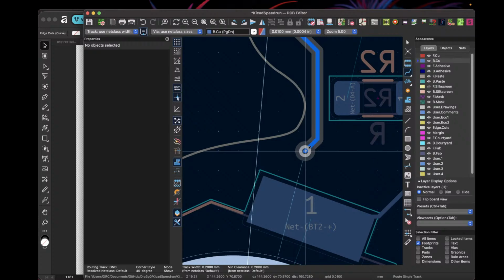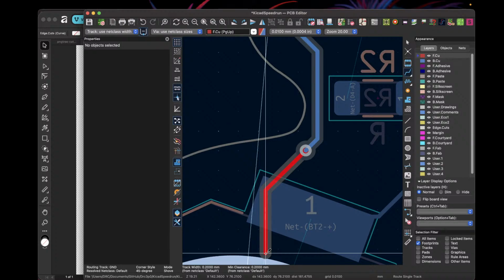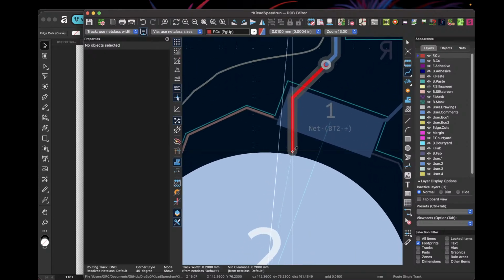Is there a downside to vias? Like, can I just easily jump over any other wires? They're usually okay. It's just, again, if you're dealing with something where maybe there are high-speed digital signals where you have to be really careful about interference, you might not want to put a via. Or if you have art on the front, this will create a tiny little divot on the front, but it's usually pretty well hidden. Like even this, you can't really tell so much. So it's just kind of a personal preference.